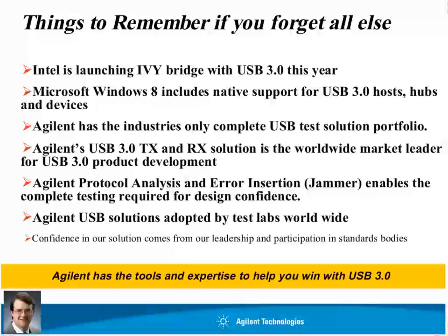So really you need more like around 9 gigabytes or maybe even more for your capture buffer as a general purpose when you're doing SuperSpeed operations. You can get by with smaller, but you have to be much more careful about the way you utilize the system.